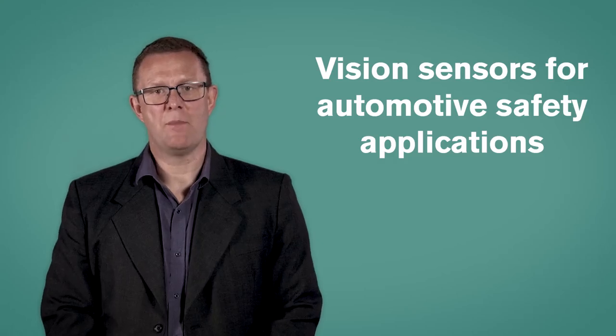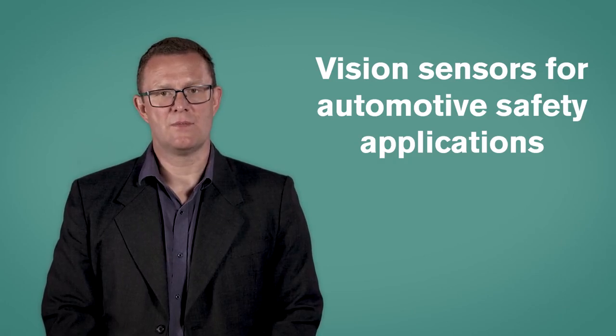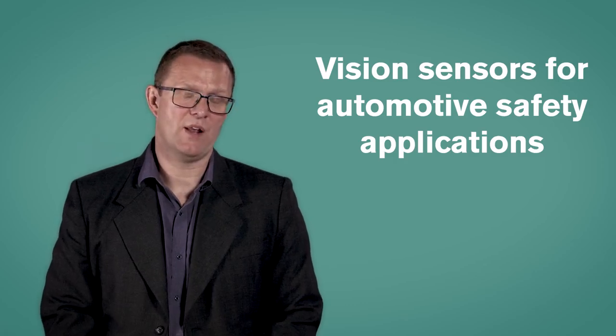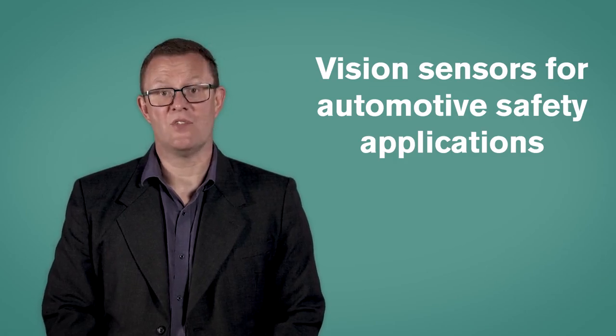This lecture gave you some basics of camera sensors for use in traffic safety and automated vehicles. Cameras are likely to continue to be a core sensor type for automotive applications, especially given the benefits of price, angular resolution, and the relative ease of object classification in camera images compared to, for example, radar. Main drawbacks are poor range and relative speed estimates.